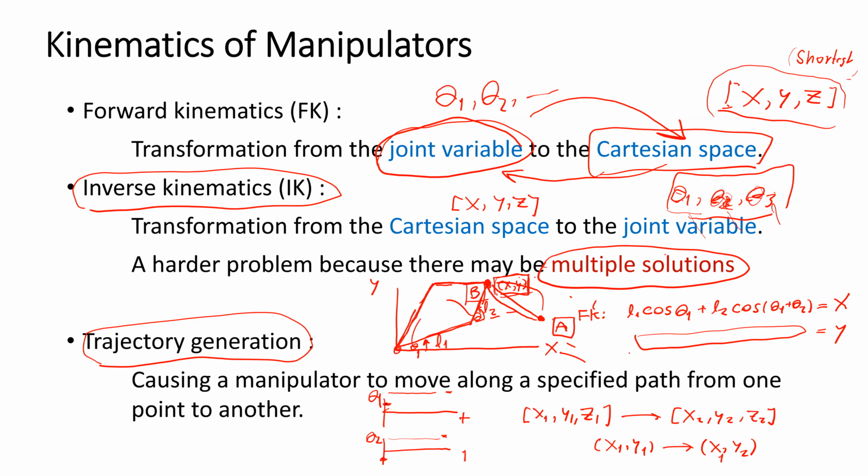And we can control the joints of the robot to move to that target position, and we can go to the target position in the XYZ coordinates. But if the robot moves in this way, when we see the robot move by eye in the XYZ coordinates, sometimes we cannot see it move in a linear path.